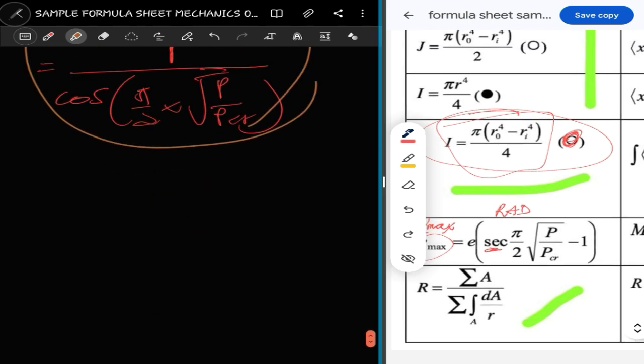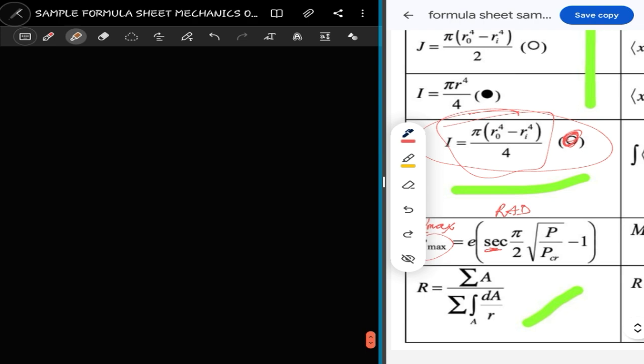And then this R that we are seeing here is basically the general formula for finding the neutral axis. This summation here is just trying to tell us that for composite figures, basically the Rn, either you see just the capital R or you see Rn, the formula is a general formula for it. The summation tells us that we are finding Rn, the neutral axis, for a composite figure.